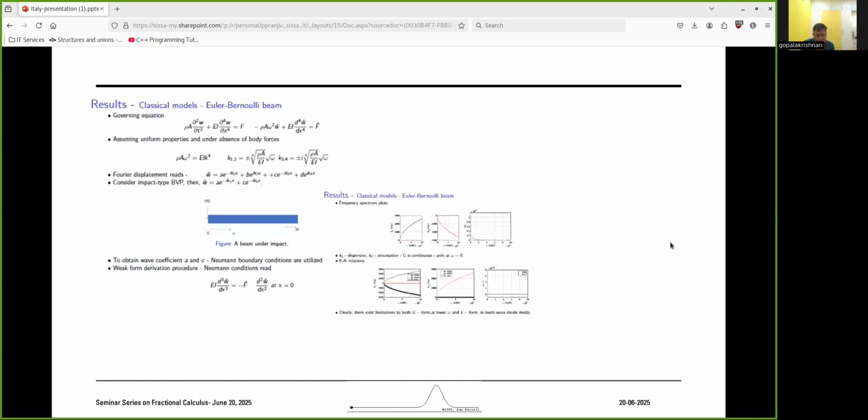The same thing we can see in the beam. Beam is a fourth order system, and one mode is completely real, another mode is completely complex. So if you feed the real part and construct the imaginary part, we can exactly get that. That means the KK relation is valid, because the regular rod and beam are stable systems. Next, please.